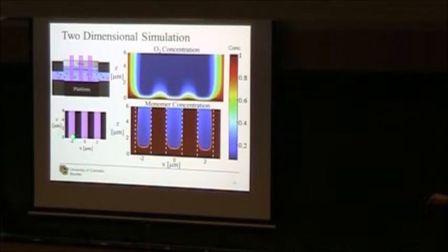However, on the sides of my exposure in this region, on those sides, I have a sea of oxygen. And so what happens is I actually get a feature shrinking at those sides. And so what that says is when I write sparse structures in particular, I'm going to get a smaller feature size than I would actually expect. And I'll actually show this later in the talk.